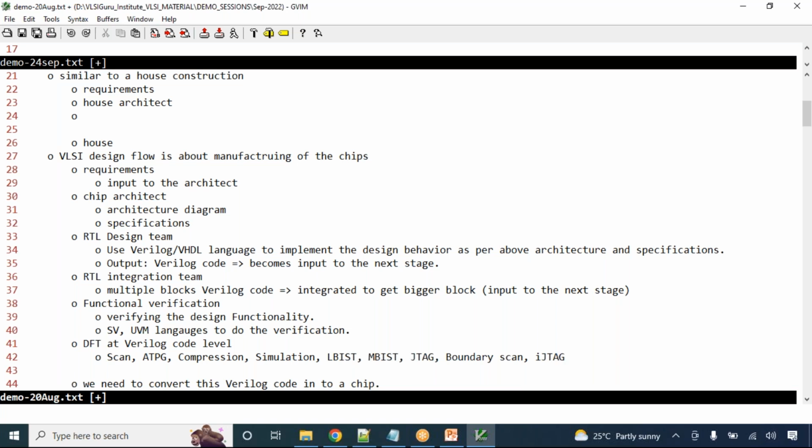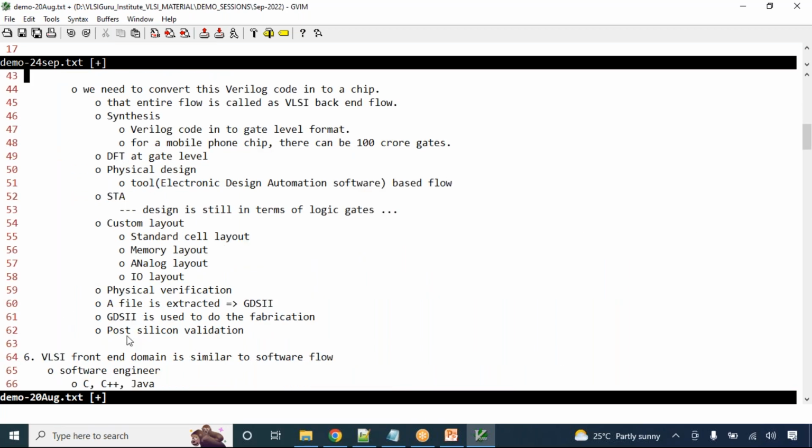Now you may ask, how do I know that 1 0? You need to ask DFT how they came up with this. These inputs are given to the final stage. To whom will they give? The post-silicon validation engineer. He is the person who is going to do this activity of putting the vectors into the chip and telling whether this chip is good or this chip is bad.